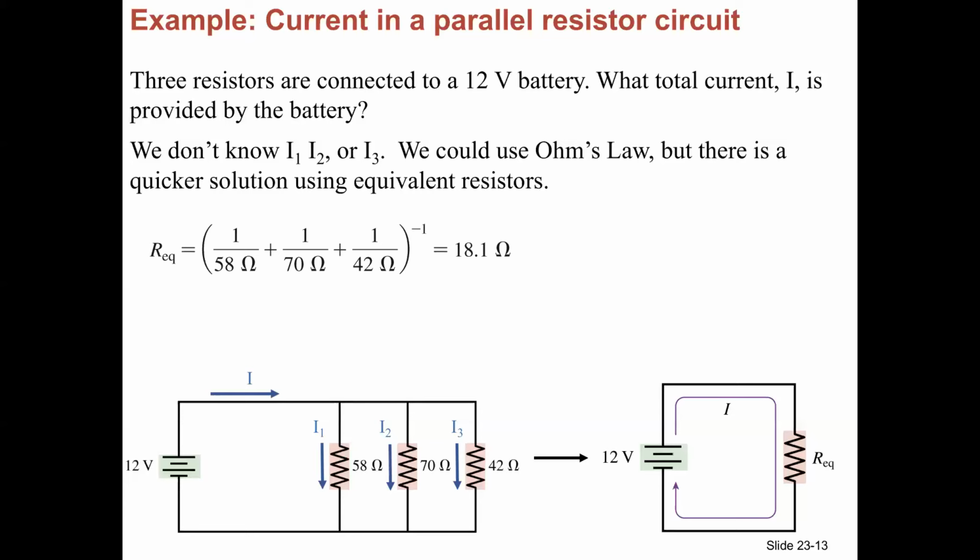All right. Cool. It seems the people who got 218 corrected their answers, now getting 2/3. Can I ask you guys just, was this the mistake? Forgetting to invert 1 over R equivalent? Okay, yeah, common, that happens a lot. That's the main common mistake with these parallel resistors.